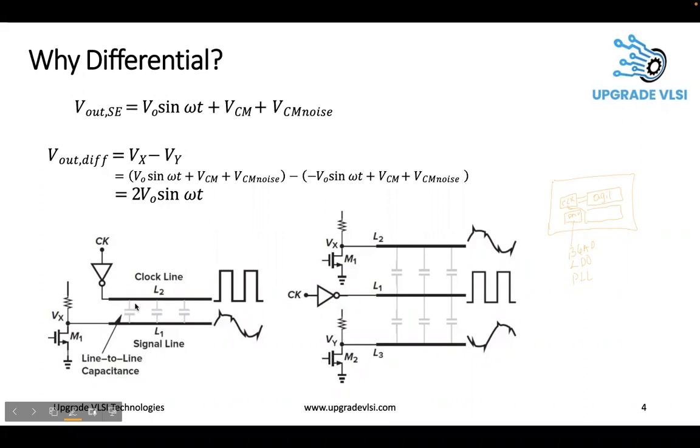So in such cases, there is a parasitic cap. This is coming because of the parasitic. Everywhere there will be a parasitic cap. Sometimes what could happen is the supply voltage also will carry some noise, so that might also be routed very close to its output, somewhere here. So that will also have some capacitor. Routing capacitance. So what happens on clock jumps?